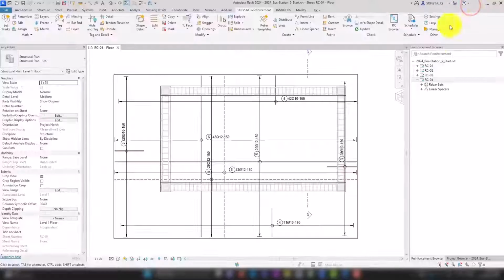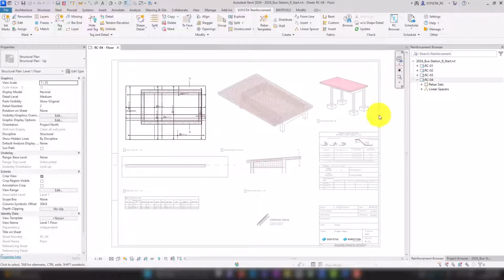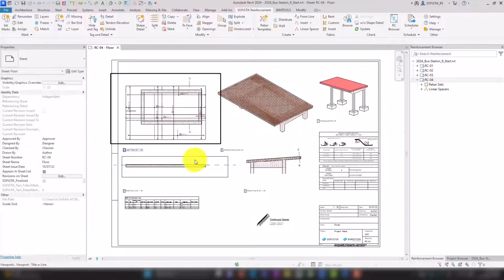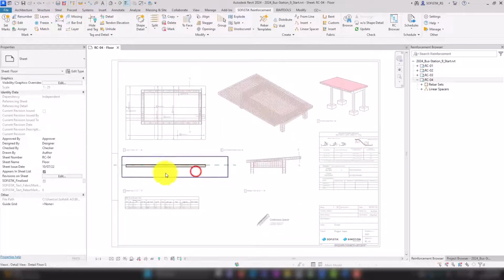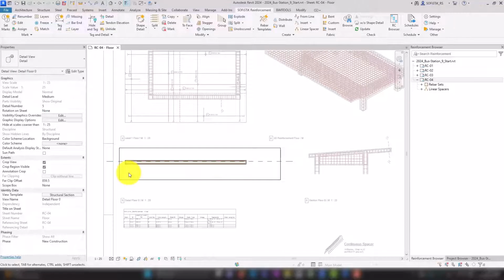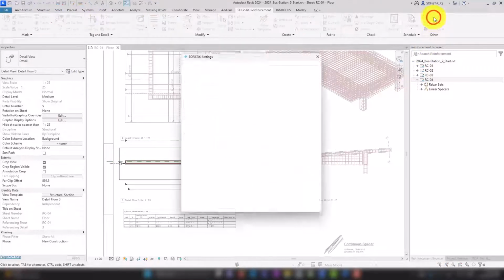Let's go back to our ceiling plan, which still needs to be finalized. As an exercise, please label the views as in the previous chapters. I recommend trying out other labeling settings or even adjusting a labeling family to your wishes in the family editor.